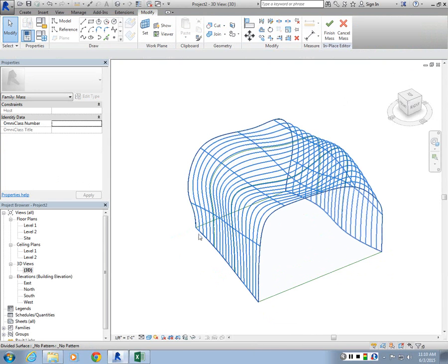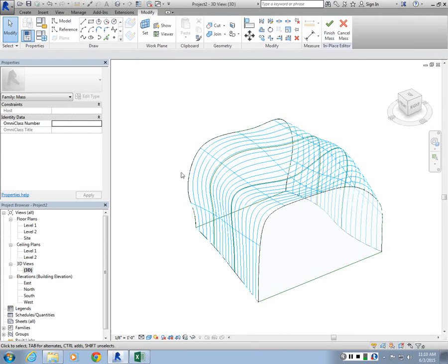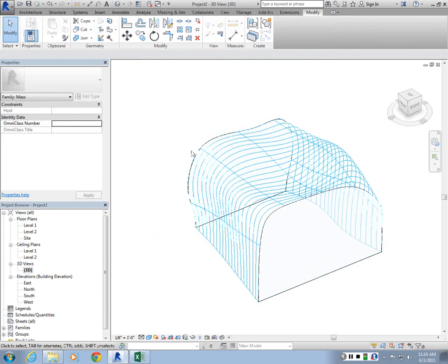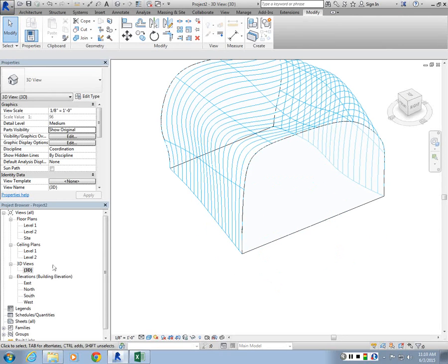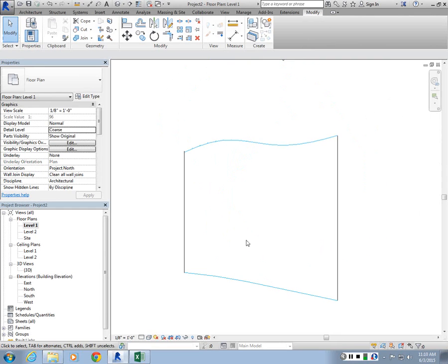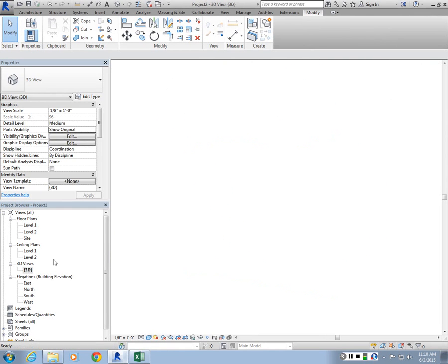And then I can make an adaptive component, a louver component, that goes through these points, which we could do tomorrow, and then basically make them into like a parametric louver system. And then when I do finish mass, it will be applied as geometric objects. And then you will see them when you draw your plans. You will see their cuts, right? How those objects intersect.